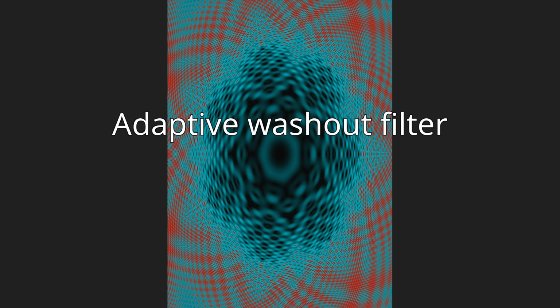The benefits of this style of washout filter can be summarized with two major points. First, the adaptive characteristics give more realistic motion cues when the simulator is near its neutral position, and the motion is only reduced at the limits of the motion system's capabilities, allowing for better use of the motion system's capabilities. Second, the cost function, or the objective function by which the washout filter is optimized, is very flexible, and various terms may be added in order to incorporate higher fidelity models. This allows for an expandable system that is capable of changing over time, resulting in a system that responds in the most accurate way throughout the simulated flight.